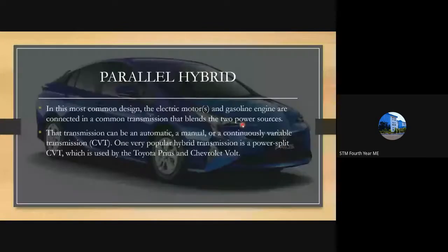During low power conditions we use the electrical part, wherein the vehicle is started at rest, providing high torque, and we get more power and less noise during that operation. Once the engine takes over at higher speeds, the electrical part is shut down and it begins charging by means of the alternator and the regenerative braking mechanism. Such a type of hybrid is known as a parallel hybrid.